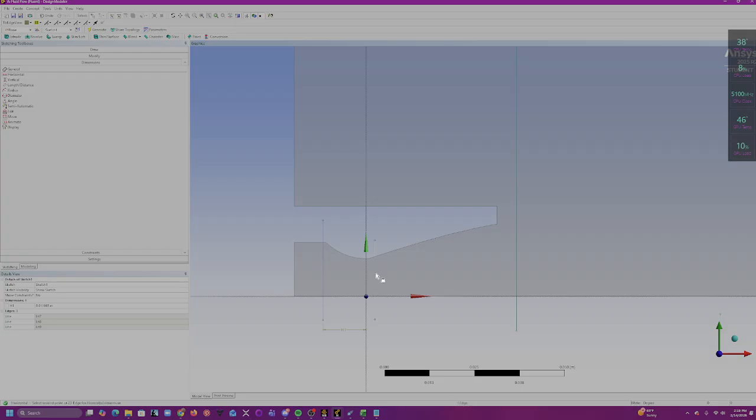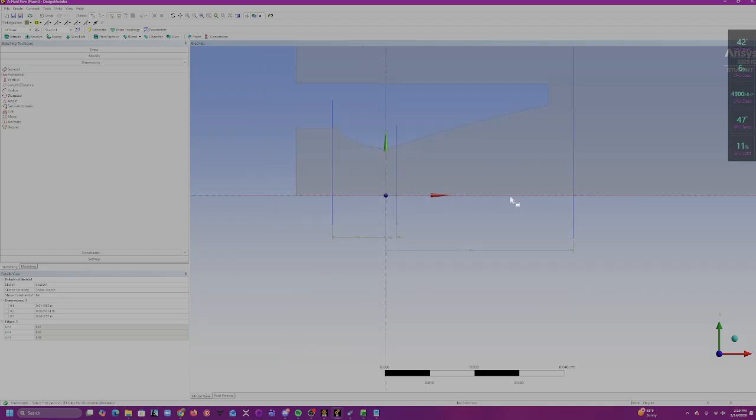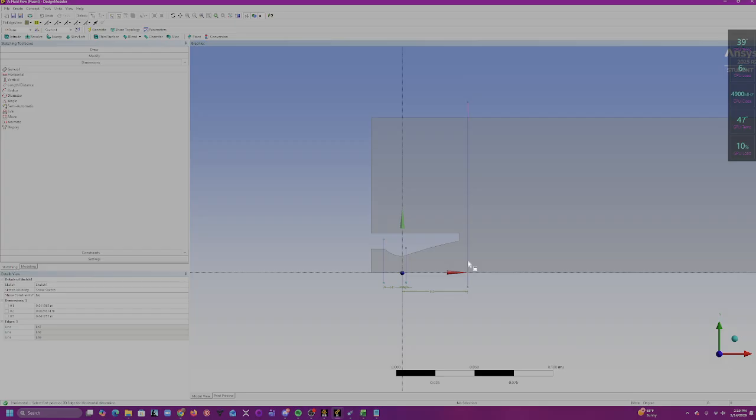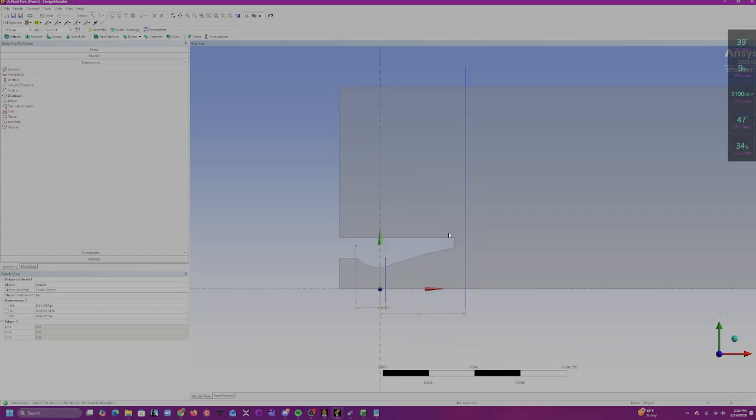So let's do the same thing for the throat line. Let's go right here. It should say H2, and then we can do another one from the origin line all the way to the exit line. So you should have something like this: 3 dimensions that are ready to be dimensioned. Again, make sure this third line right here is cutting all the way through the object.